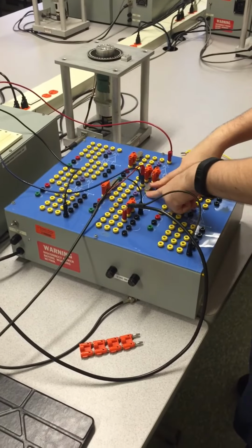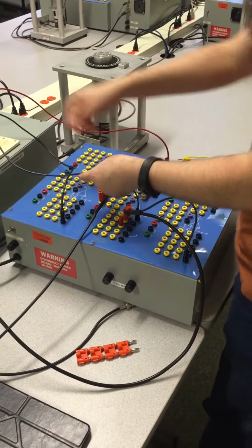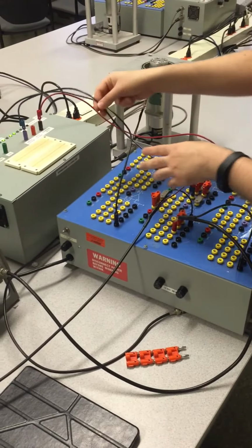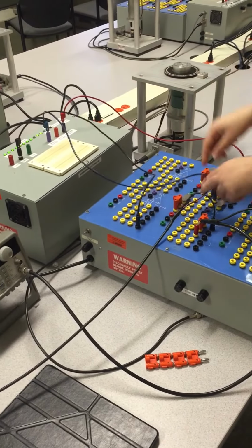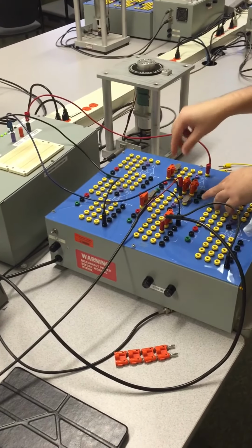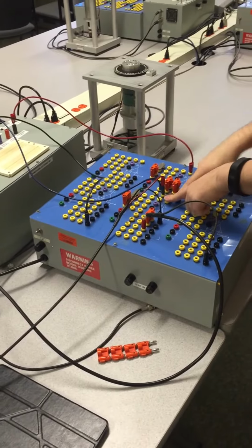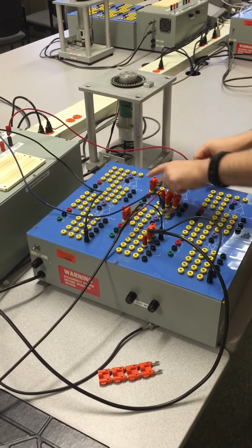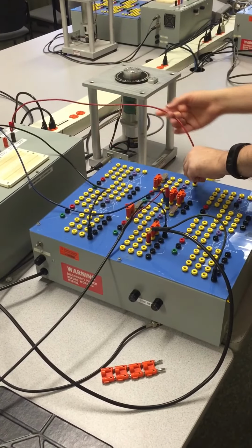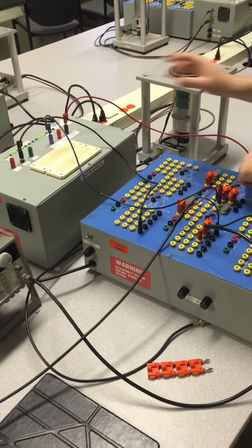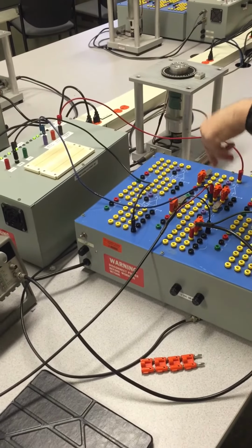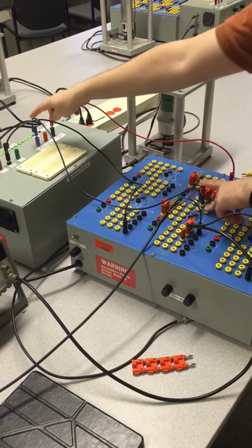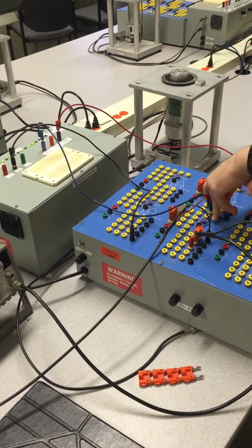The feedback is coming from what? The feedback is coming from the angle output. This is what I want to control, the angle output. So it is coming as a feedback. The inverted signal and the feedback are summed together to form my control signal that is going to the command input. So if the input signal and the angle output are the same, the difference is 0.